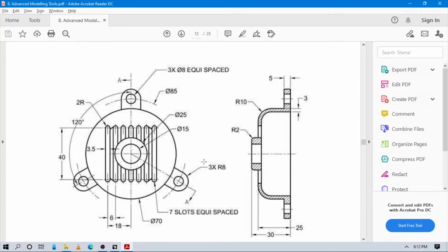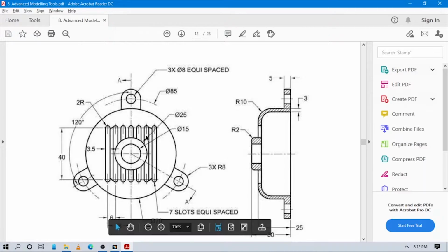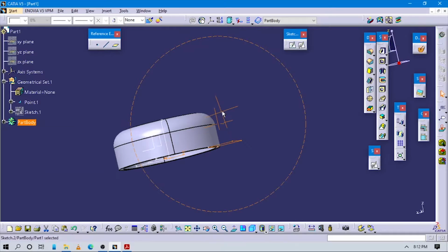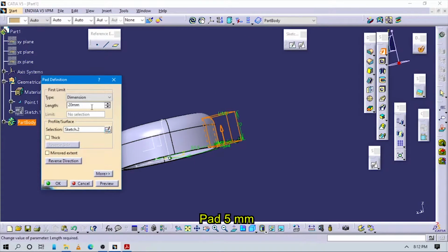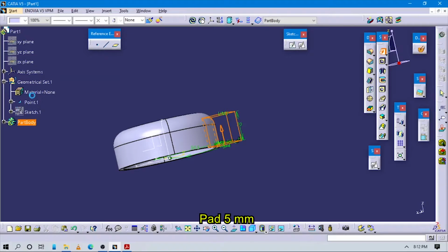Make sure what the pad value for this is. So here you can see the pad value of this is given in this section. Actually here the offset section is given from this to this. The pad value of this flange is 5, and from this 14 to up, so give 5 here.